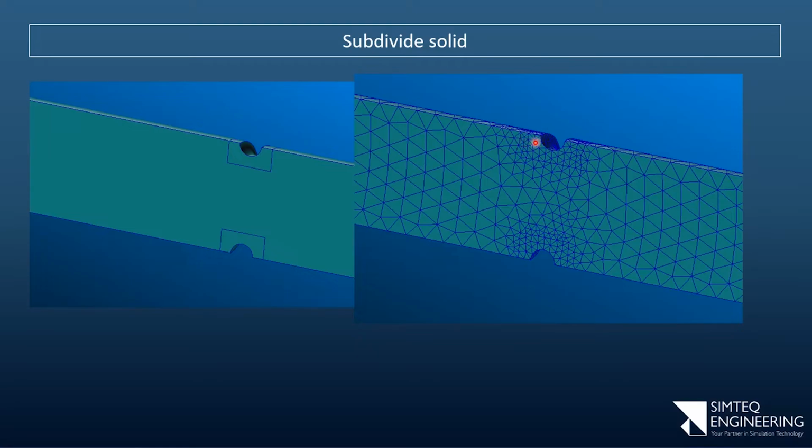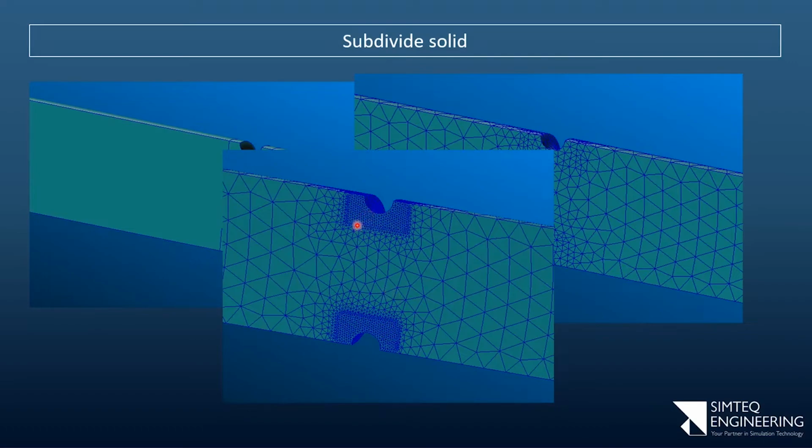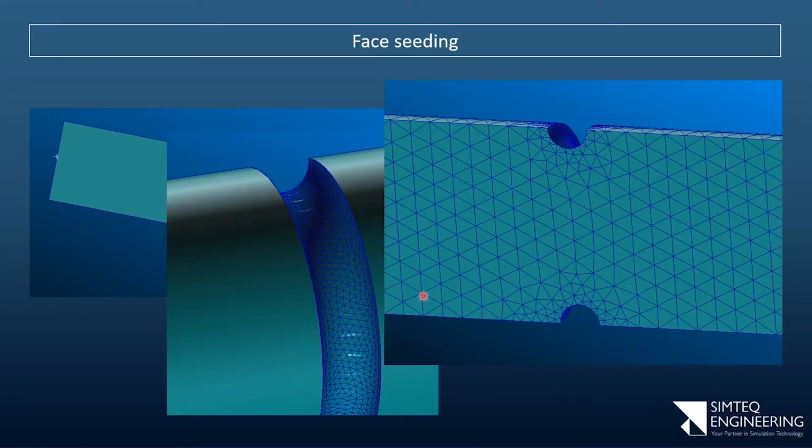So it doesn't need to be this cutout. It could have been a radius kind of cutout, whatever kind of cutout is easiest to use and easiest to set up, and would result in a reasonable amount of elements, would work. Just as an example, I took this one to an extreme, where I meshed that section extremely fine and then still transition to the same element size that I have on this model. So in this case, I have a lot of control, whereas if I go back to this slide, I have no control over how far this finer mesh will extend.